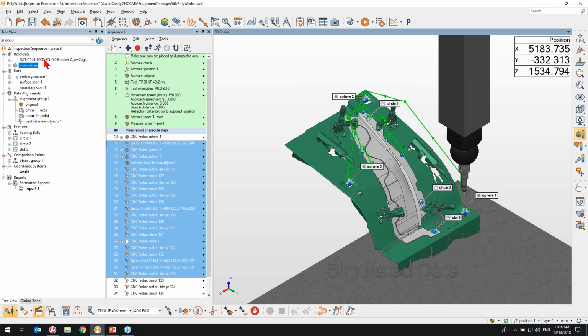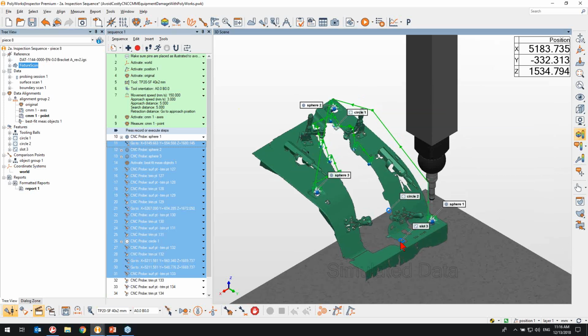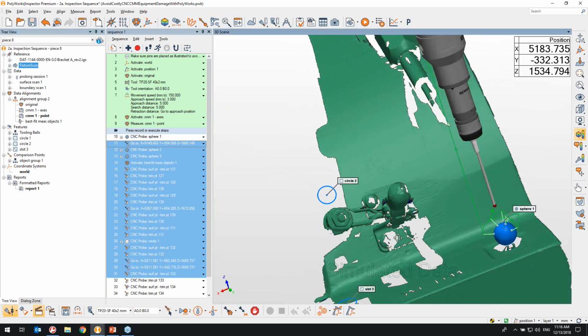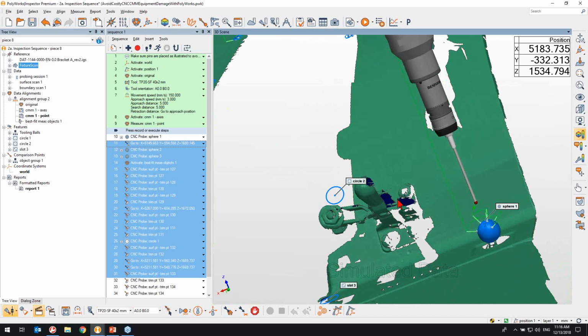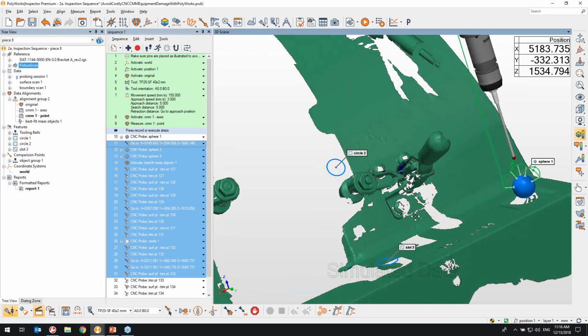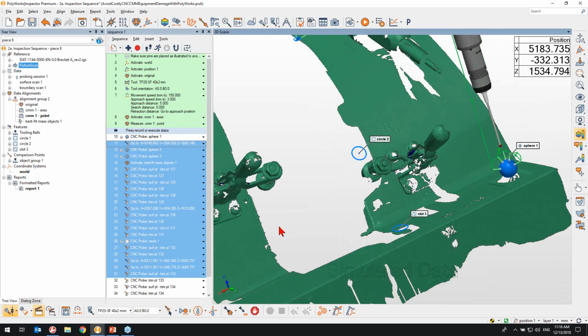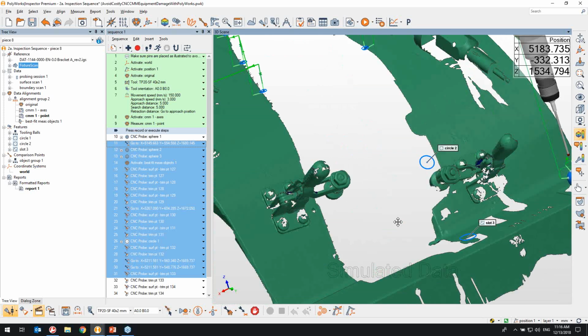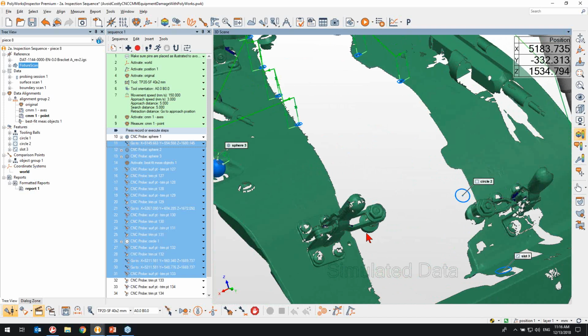So in this particular example, you will see that it is not a perfect scan, not even close. You'll see that I didn't even scan perfectly all of the clamps. There's holes in many of the areas, so you don't need any watertight scan. You can even just focus on the areas that you know might cause potential collisions.